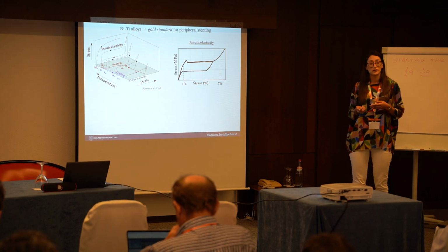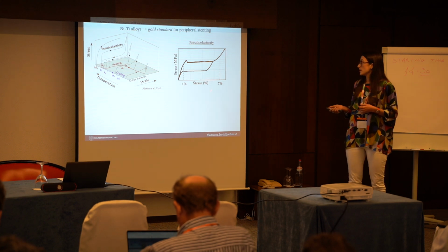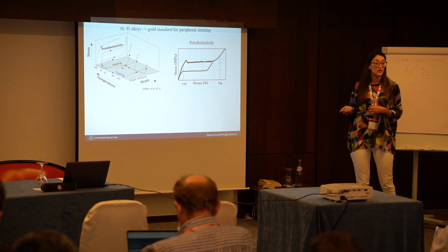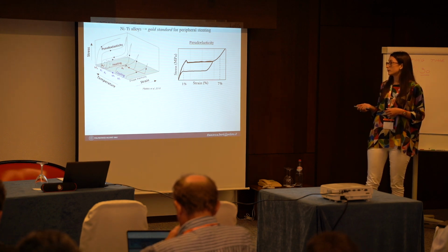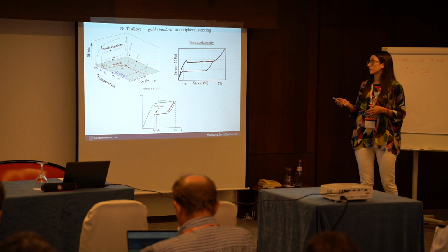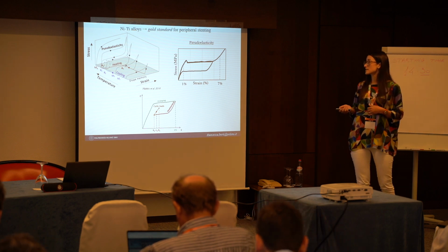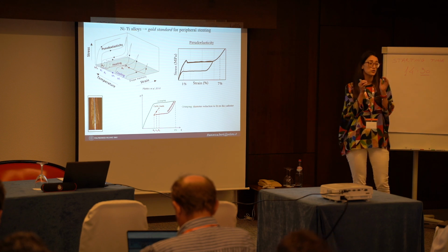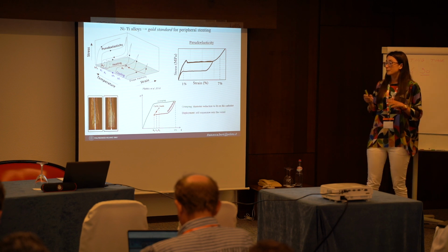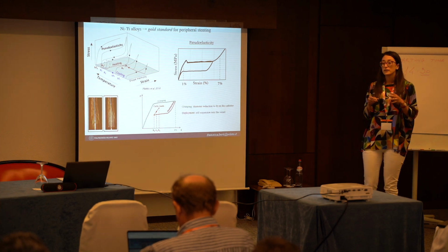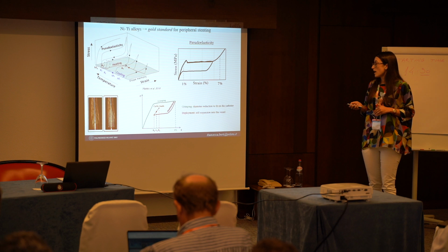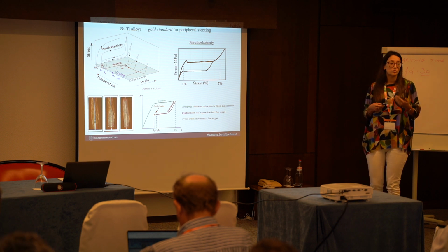These stents are made of nickel titanium alloys, which belong to the shape memory alloys. These are temperature-dependent materials, and as you can see from this plot, they are characterized by strongly non-linear mechanical behavior, and in particular, they can cover elastic deformation up to 7–8%. That is pretty useful in the lifetime of a stent, because stents first need to be crimped, so their diameter needs to be reduced to fit on the catheter in order to be inserted inside the body. Then, when they arrive at the location, they need to be expanded, and at this point they cannot expand freely because they encounter the artery, and only at this point do the real cyclic loads due to gait start.